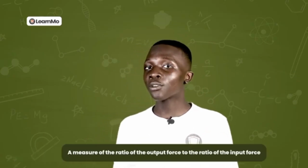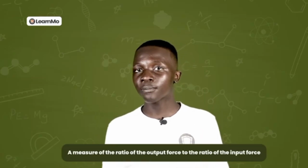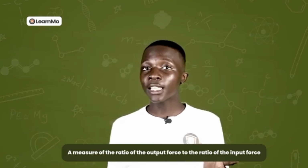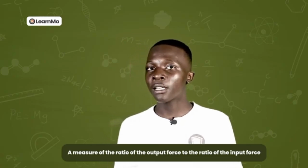Well, mechanical advantage is a measure of the ratio of the output force to the input force in a system. It is used to analyze the forces in simple machines like levers and pulleys. Despite changing the forces that are applied, the conservation of energy is still true, and output energy is equal to the input energy, and it carries no units. It is calculated as mechanical advantage is equal to load over effort.